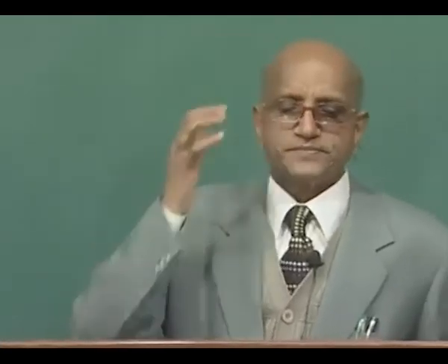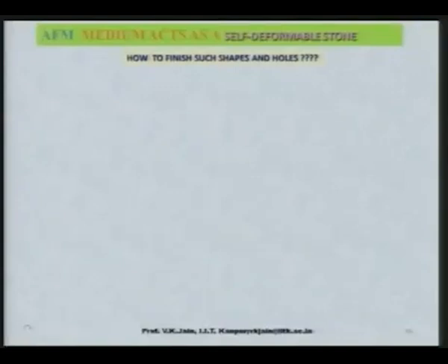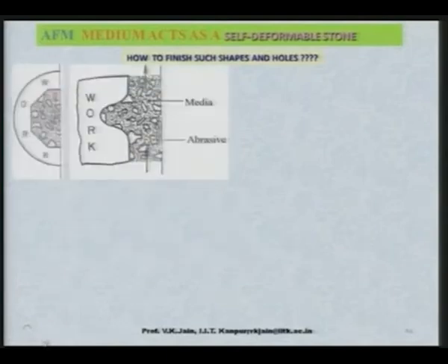Now, let us see the medium in the abrasive flow finishing process or abrasive flow machining process. The medium in the AFM process acts as a self-deformable stone. How to finish different kinds of shapes which are shown in this particular slide is really a problem. Here you can see the octagonal hole shape which you cannot finish by normal finishing processes. Even with MAF you cannot apply that one here.